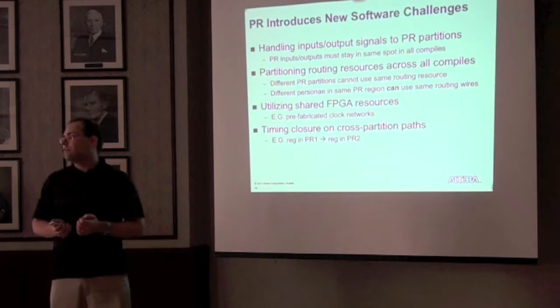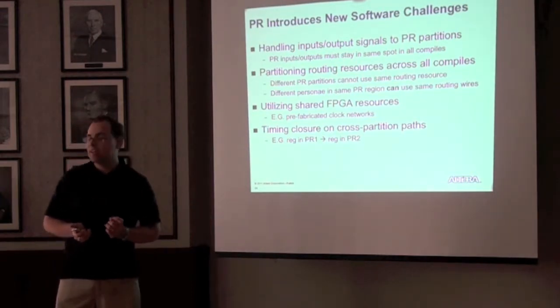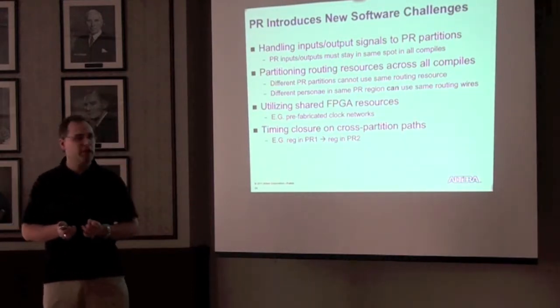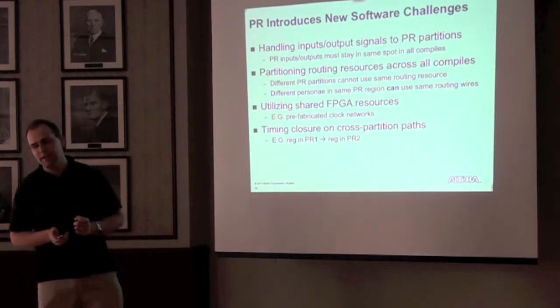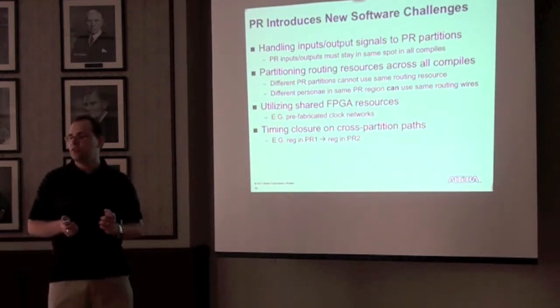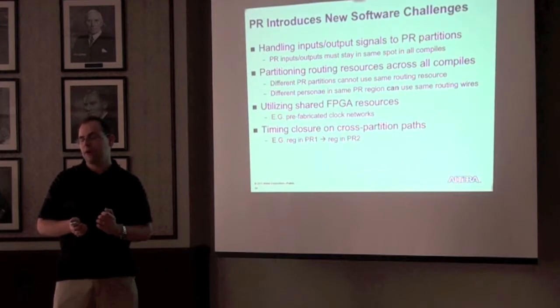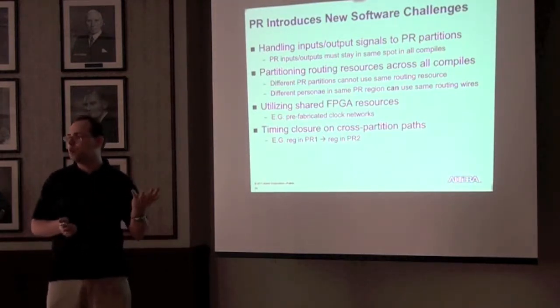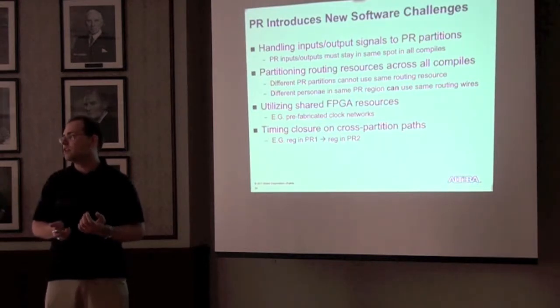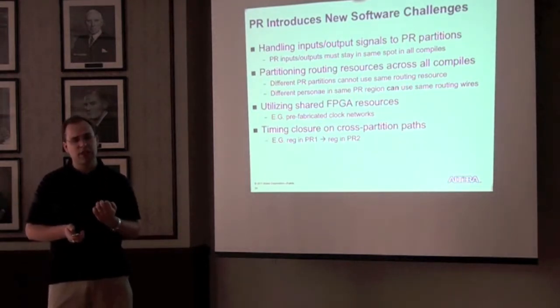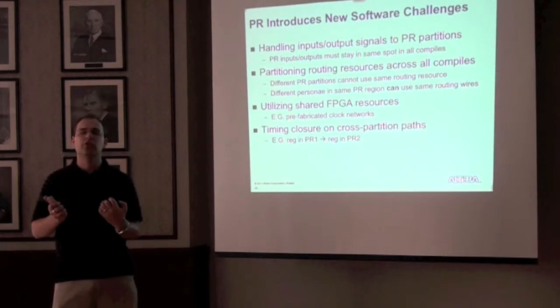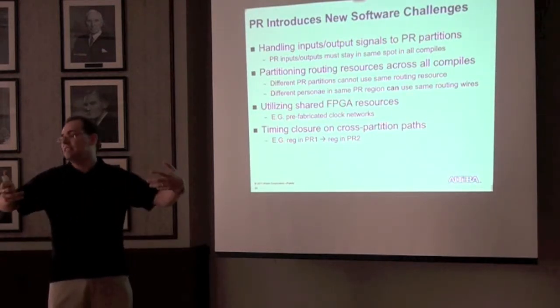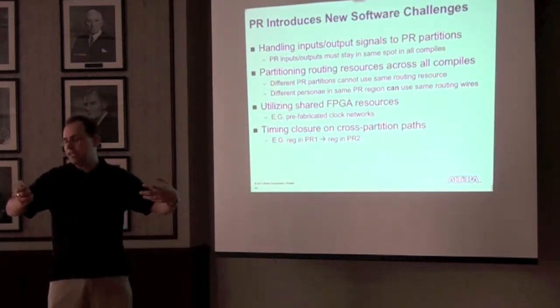Certain shared FPGA resources, such as the clock networks, are an especially difficult problem, and I'll go into more detail on that later. And finally, we provide the ability to do timing closure of cross-partition paths. So suppose you have a register transfer where the source register is in one PR partition and the destination register is in another PR partition. That represents a challenging timing closure problem because there's no guarantee that the CAD tool will actually see the full path in any given compile.